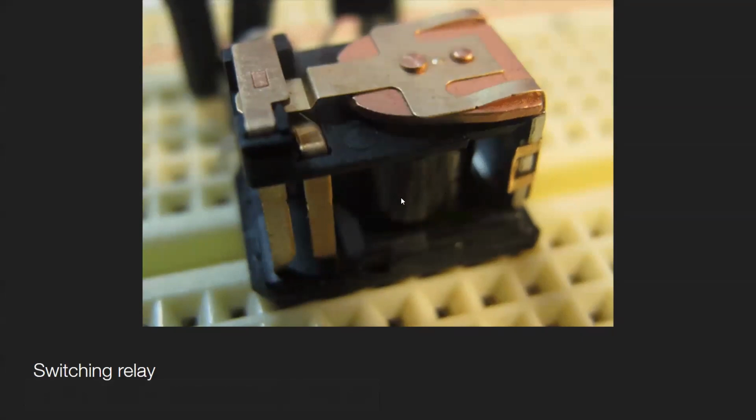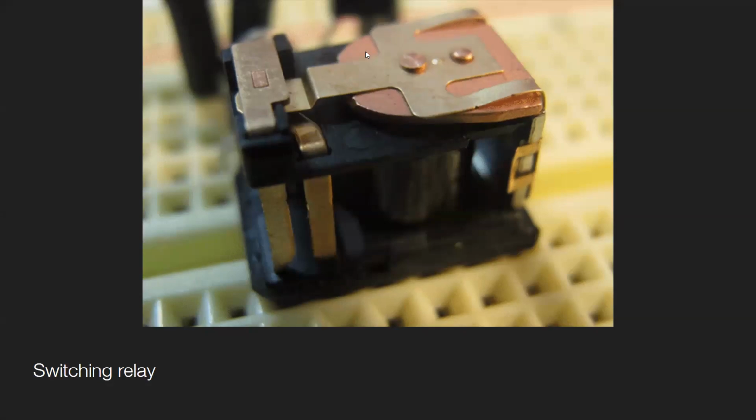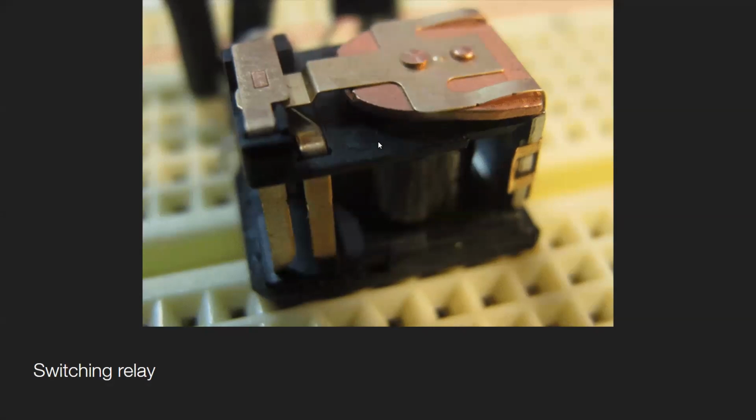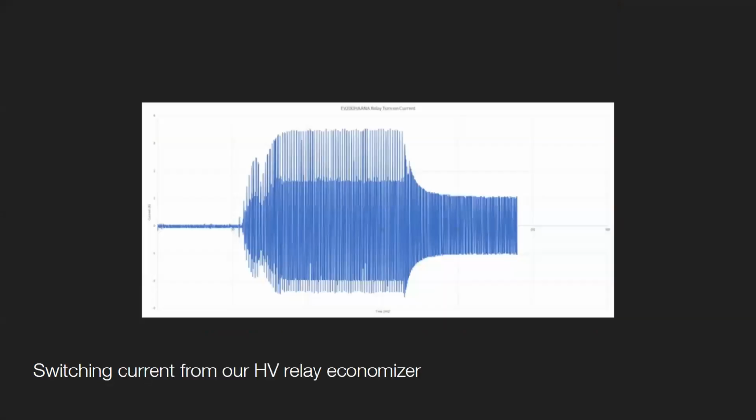And this is proportional to the current. So this means that when you want to close the relay, you need a higher current initially, and then just to hold it closed, you don't need to provide as much current. So if you want to save power and not waste it by having current flow through this coil, you can have relay economizers that reduce the amount of power that's used by the relay coil. So this is an image of the current. This is a graph showing the current that's drawn from our relays.